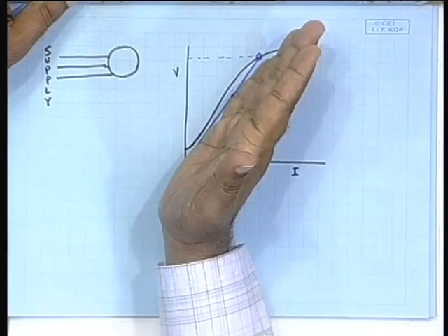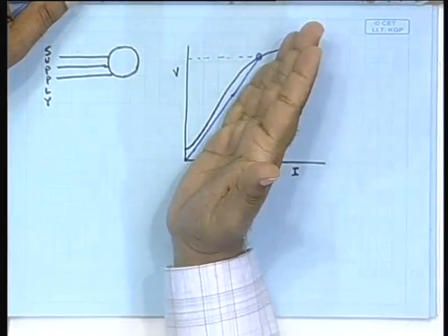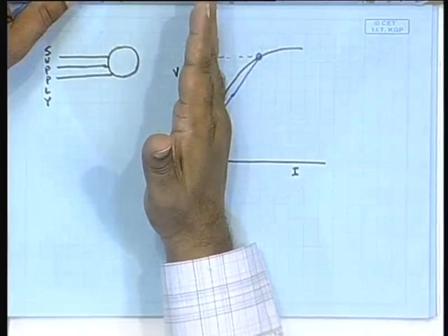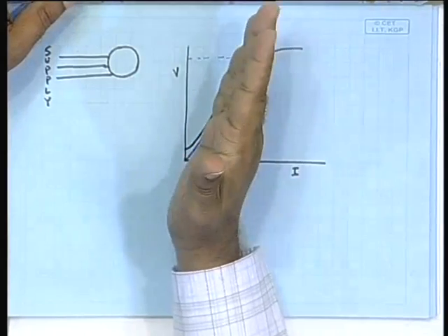Why does it happen only beyond a certain speed? That's because if the speed is low, the capacitor characteristic will be like this. If the speed is low, why? Because the capacitive impedance depends on the frequency. When it is rotated, yes, it generates a voltage, but that voltage has a frequency, and the value of the capacitive impedance depends on the frequency, right.